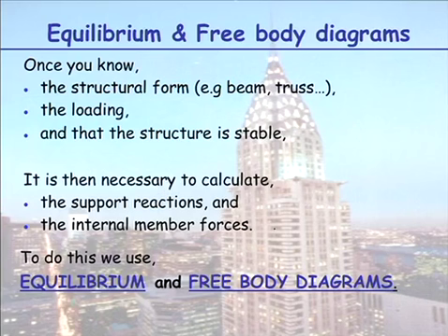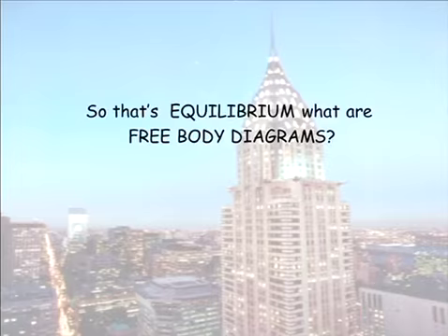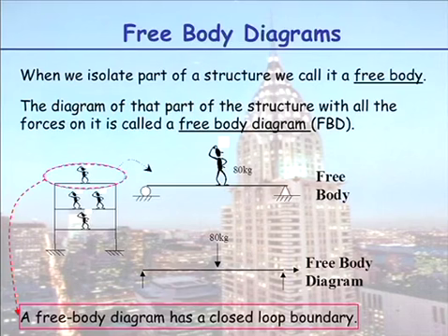Now I want to introduce you to free body diagrams. So what are free body diagrams? People that have done their tute already today will have covered this, so I'll just cover it again. When we isolate part of a structure, we call it a free body. So in this instance here, I'm isolating the top floor of the building with the man on it. Now the diagram of that part of the structure with all the forces on it, we call a free body diagram.